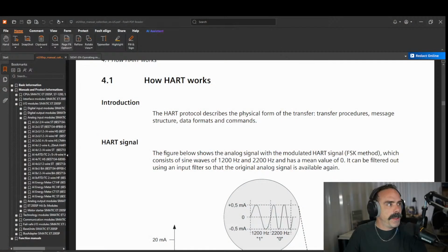But let's go back to the HART module, and I think it's 64. Yeah, so Mika's helping out. 64, I think is what it is, and honestly, 64 input modules would take up a lot of space. So you're probably not going to be able to physically get much more in there. I will say, just kind of an aside, if you want to make your panel builders and your electricians out in the field absolutely hate you, shove too many of these I/O modules into a small box.